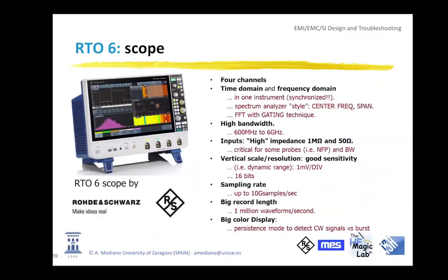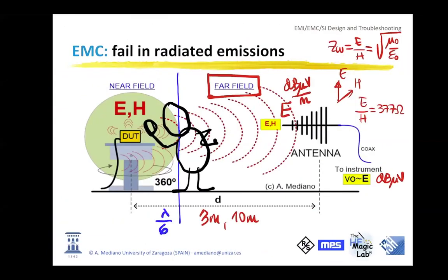If we go to the previous slide, for example, I have the antenna in vertical polarization. So this antenna will be very sensitive to electric fields that are going in vertical. This electric field is propagated through the space and attenuated, but when it reaches the antenna, it creates a current in the rod, and this current is what we are measuring in our receiver. But if the electric field is horizontal, because the antenna is in vertical orientation, we will not be able to create this induced current, and the measurement will be theoretically zero, okay?